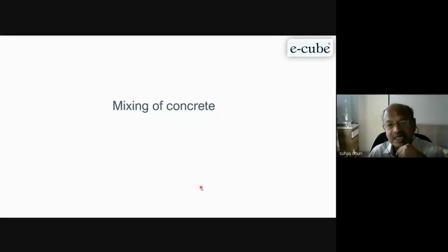If you see there, they always write it is a densified material, because microsilica is a very fine material. Average size is 1 micron or 2 micron and very difficult to handle at the undensified stage. So for the construction industry, it comes in densified stage.